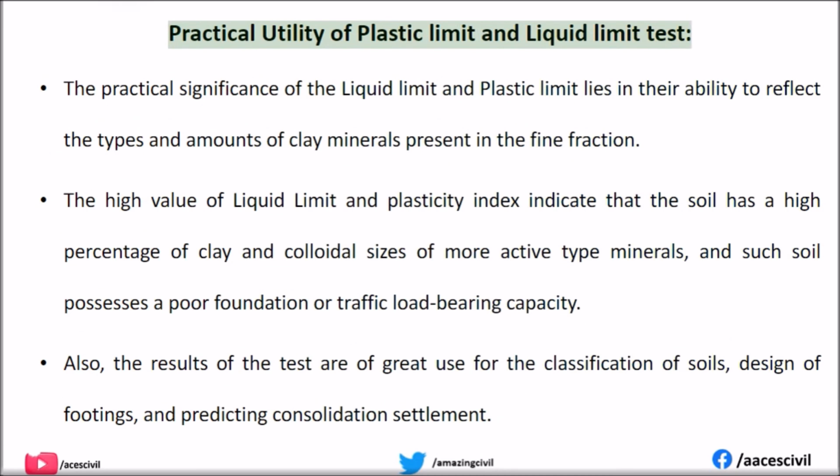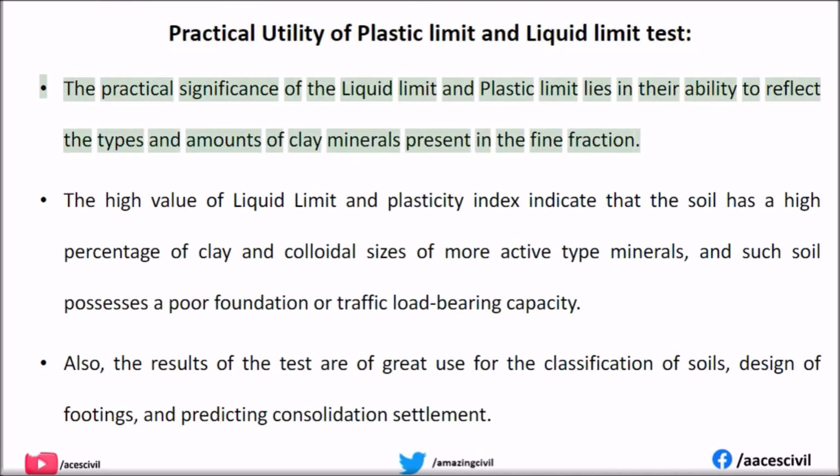Practical utility of plastic limit and liquid limit test. The practical significance of the liquid limit and plastic limit lies in their ability to reflect the types and amounts of clay minerals present in the fine fraction.